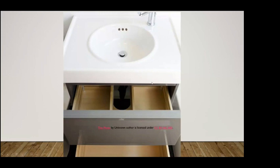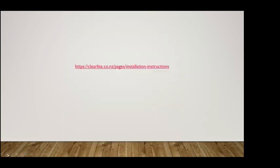That's where a little bit of problem solving comes in. Sometimes you can cut them really short and put a brass elbow or something, and that'll fix the problem. It gives you enough to make it work. But sometimes things are tricky. There are so many different products out there for different situations, like diaphragm traps or different styles of traps that aren't as bulky. So some of those new products can sometimes get you out of trouble.